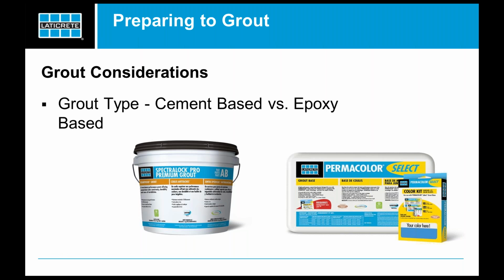So which grout should we use? Can we use either, if you will, cement-based or epoxy-based? And the answer really is yes, you can use either one. For best performance, especially on floors, the epoxy grout usually works best. It's going to be your more durable one, your more stain-resistant one, and more color-fast. And again, ideal for these thin joints that don't have a lot of body to them.